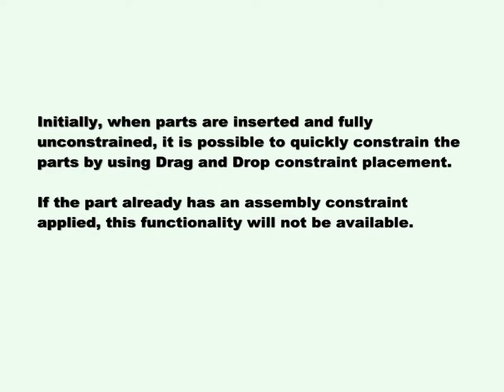This video will cover drag and drop assembly constraints. Initially, when parts are inserted and fully unconstrained, it is possible to quickly constrain the parts by using drag and drop constraint placement. If the part already has an assembly constraint applied, this functionality will not be available.